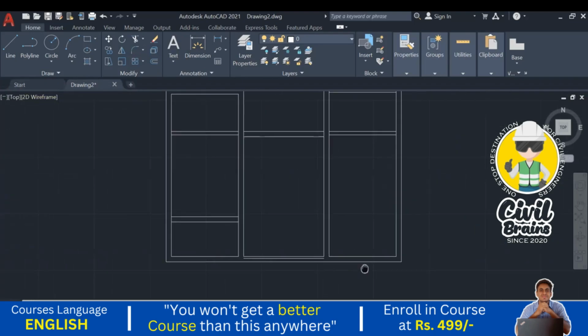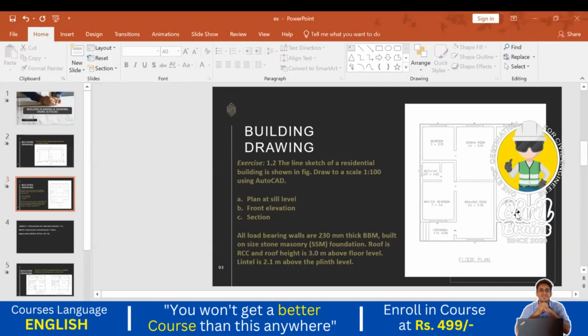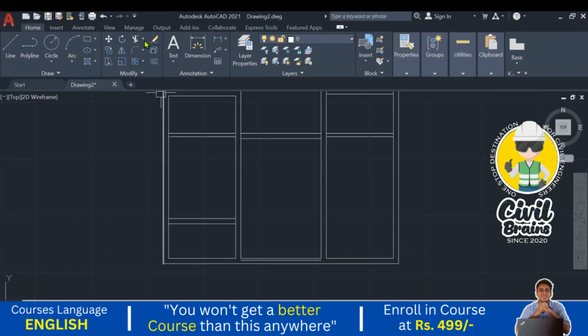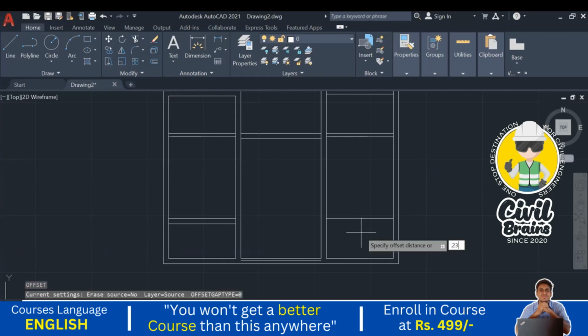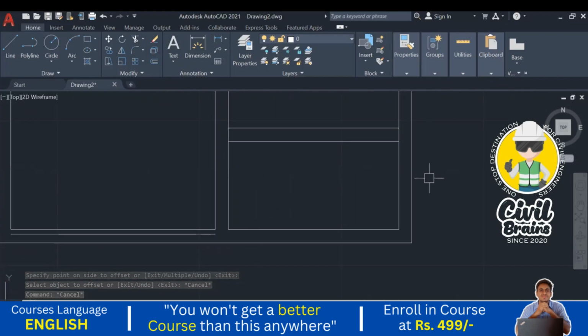Okay, next from here there is one more room. What is the dimension? 3.60. I just come here and go to the offset, 3.60. Okay, offset 0.23, and here you can see this is our extra portion, what we need to delete, what we need to trim.